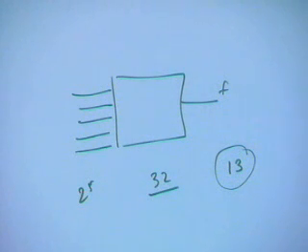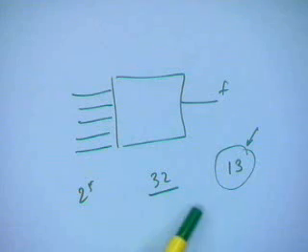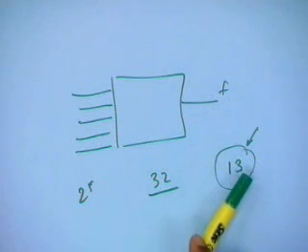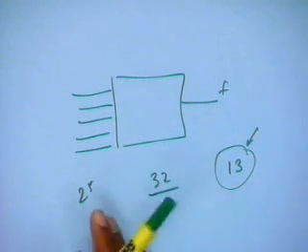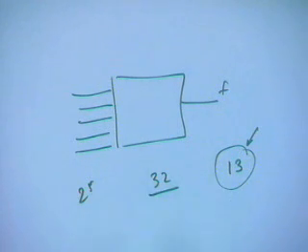As we discussed in the last class, there is an aliasing problem. Maybe that particular min term which was expected to be 1 is 0, but some other min term is 1. And because of that, the number actually turns out to be 13, but the circuit is still faulty. But we have to make sure that such aliasing doesn't happen very often. So, if that doesn't happen, the count 13 becomes the signature for this particular function.